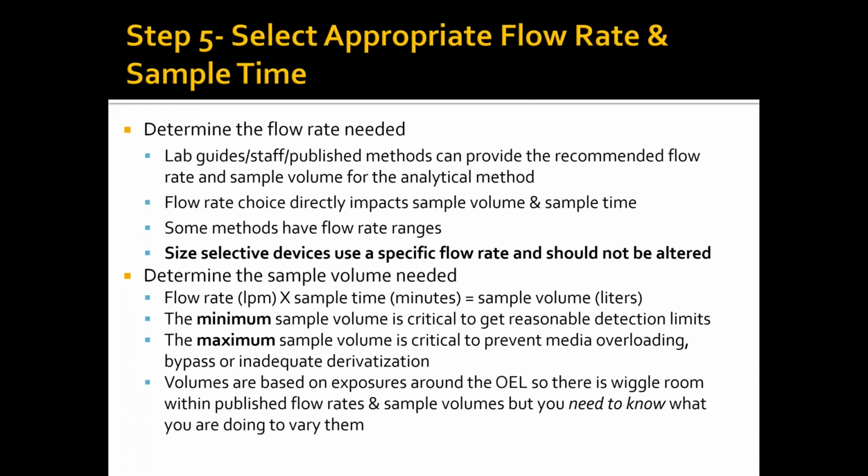Talk to the lab and ask them in their experience, if the published volume is 240 but you're expecting really, really low exposures, could you extend that out and minimize the number of media and therefore your cost, because you're not having to have as many samples analyzed.